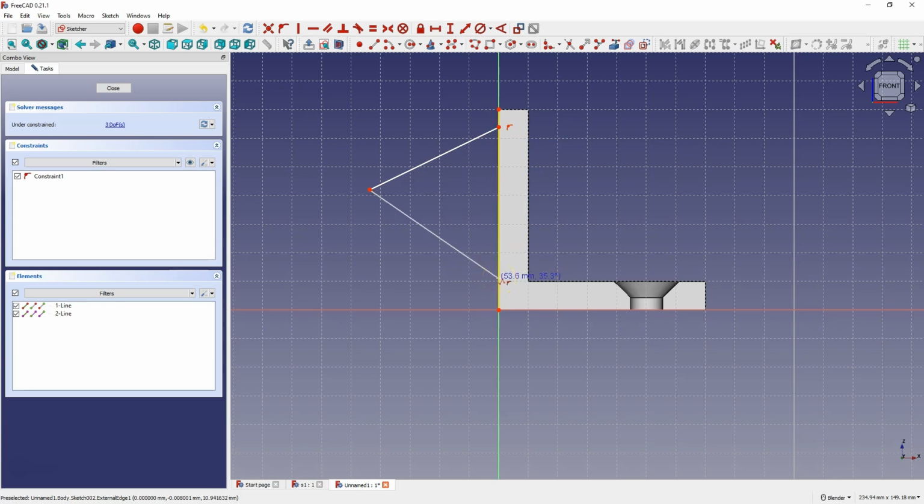That is, when this line is highlighted in yellow, then click to constrain the point of this line to this line, and the drawing of the polyline is still active, and finish the drawing at this point, and right-click to finish. Again, right-click to cancel the command to draw the polyline. And now let's add the dimensions.